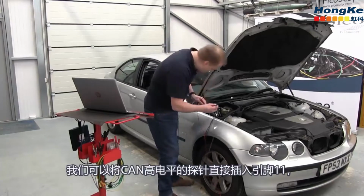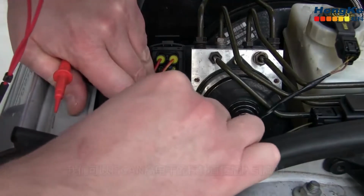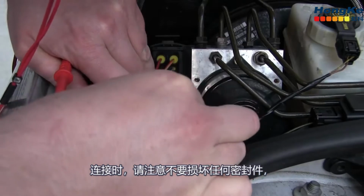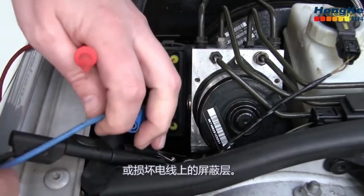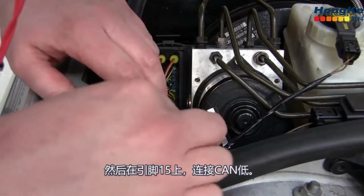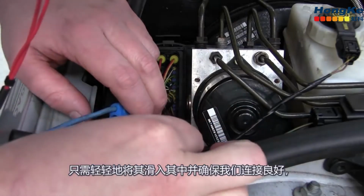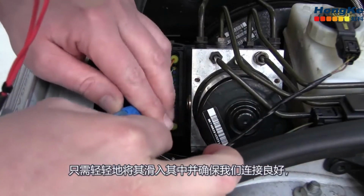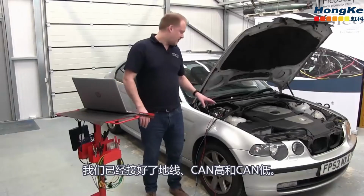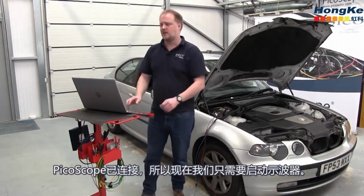We can do CAN high, which we can put straight into pin 11. Now obviously when you do this you have to be very careful not to damage any seals or damage the shielding on the wires. And then on pin 15 we've got CAN low, so just slide that in there gently, make sure we've got a good connection. Lovely. So we've got earths connected, CAN high, CAN low, Picoscope connected.